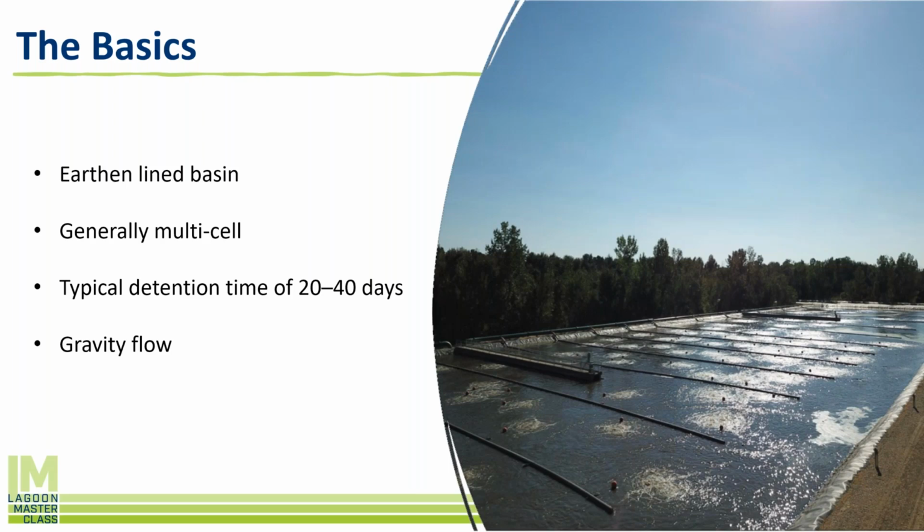Wastewater lagoon systems generally are multi-cell, unless it's an interesting or a more uncommon use case, like a storage pond or an EQ basin. If it's used for process, it's almost always going to be multi-cell, either one large basin split up with baffles or multiple disparate basins daisy-chained together.